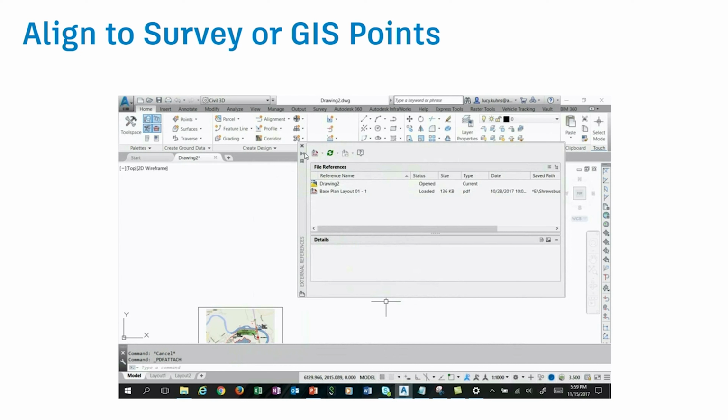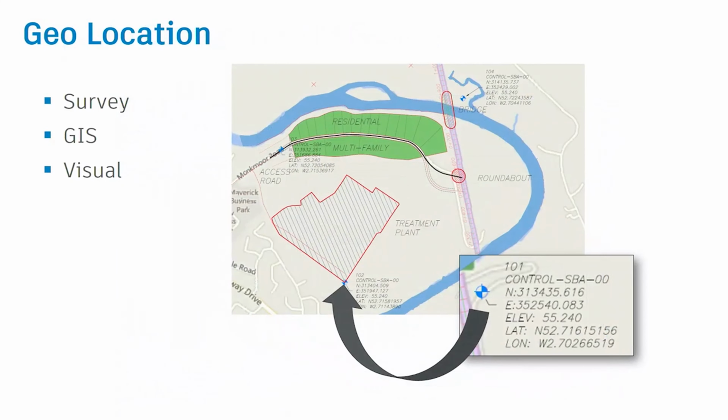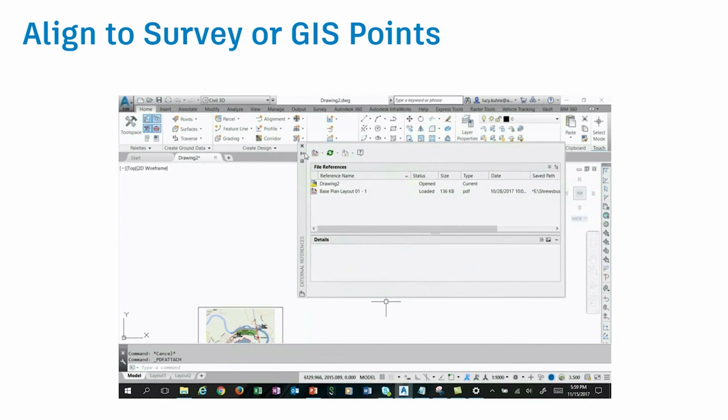We're going to take that and we're going to turn that PDF and the extracted vectors into a true geo-referenced system. Okay, what command in AutoCAD am I going to do that with? Okay, rubber sheet, okay, but even more simple. Align, the good old align command. So we can do it either visually or we can do it more precisely with survey control.